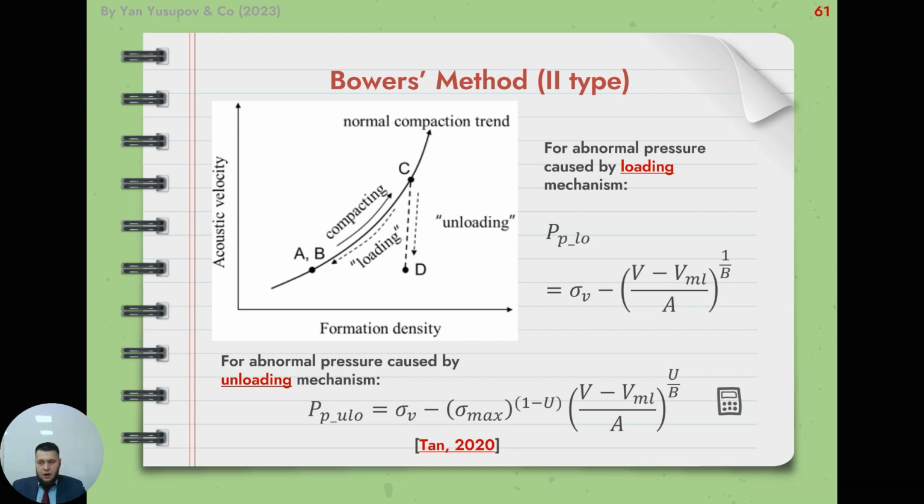He proposed that sonic velocities and effective stress have a power relationship, and because effective stress and P-wave velocity don't follow the loading curve in the uplift or unloading process, a higher velocity appears on the unloading curve than on the loading curve at the same effective stress.